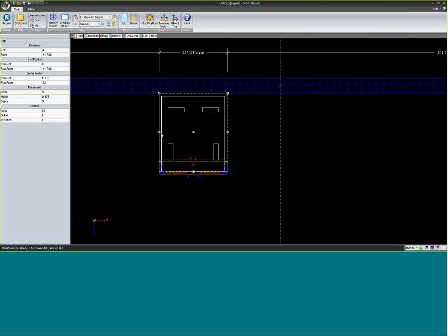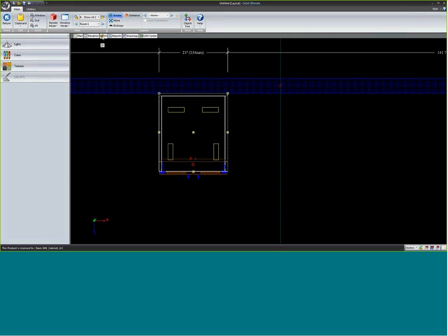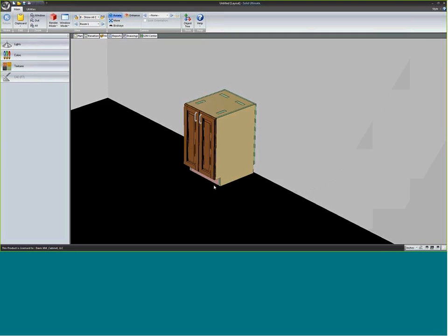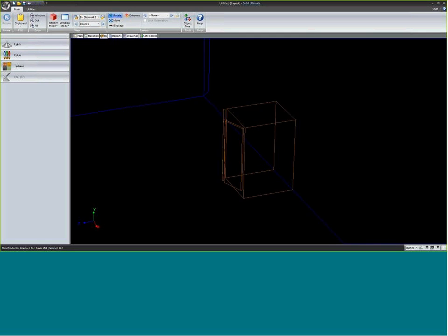Number one, it is a three-dimensional object, so it does not like two three-dimensional objects to occupy the same space. Sometimes in layout you might have a leg or a foot that shows up underneath this cabinet in the toe kick area. You and I know that that foot will fit under there, but Cabinet Vision sees that cabinet.